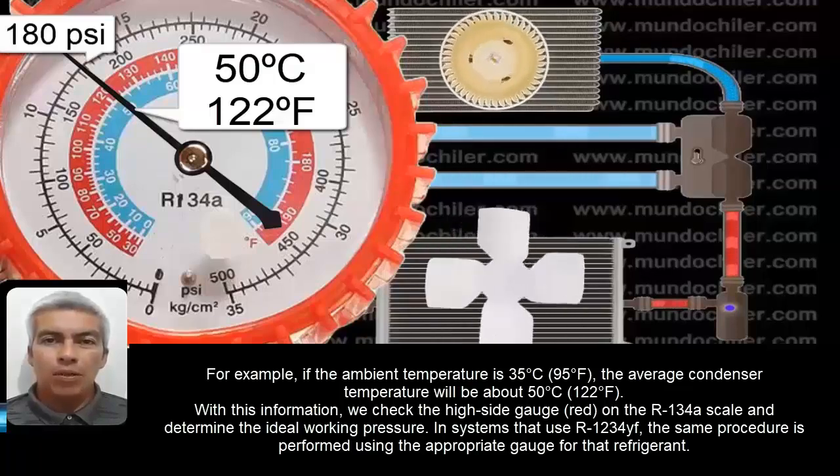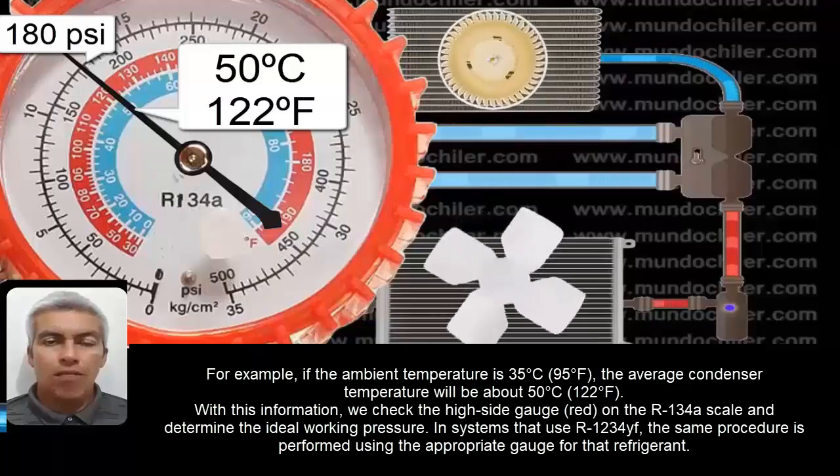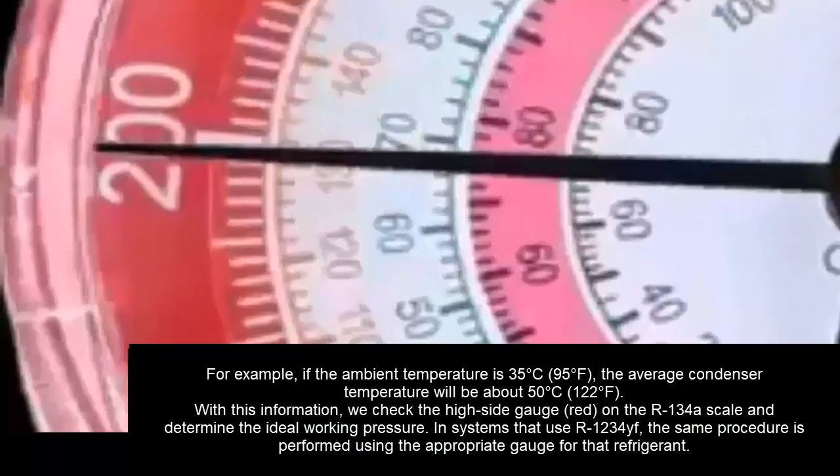With this information, we check the high side gauge on the R134A scale and determine the ideal working pressure. In systems that use R1234YF, the same procedure is performed using the appropriate gauge for that refrigerant.